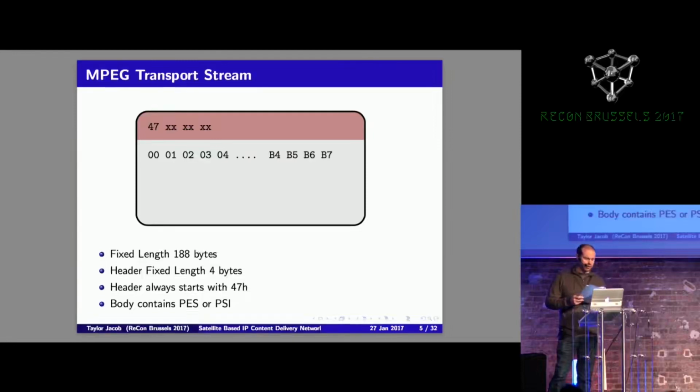Each PID will carry a specific type of traffic. It can be a single video stream, audio stream, program metadata, or other data traffic. The PIDs are how a set-top box or other component can filter out the content not relevant to their operation. For example, a digital video channel will be made up of a few PIDs. Generally, you will have one PID used for the video stream, another for the audio track, and potentially others for subtitles or captions or whatever you call it in Europe.